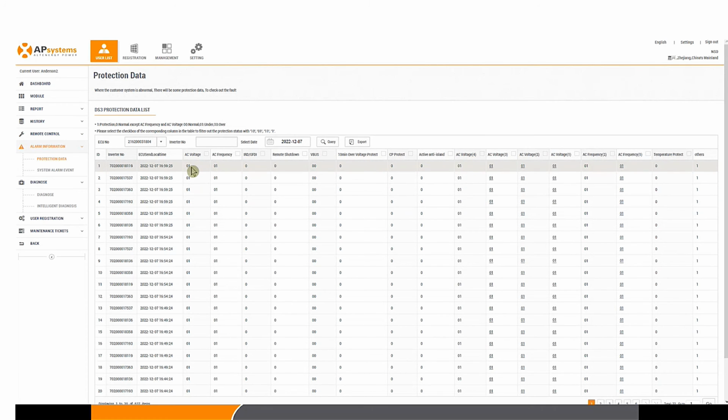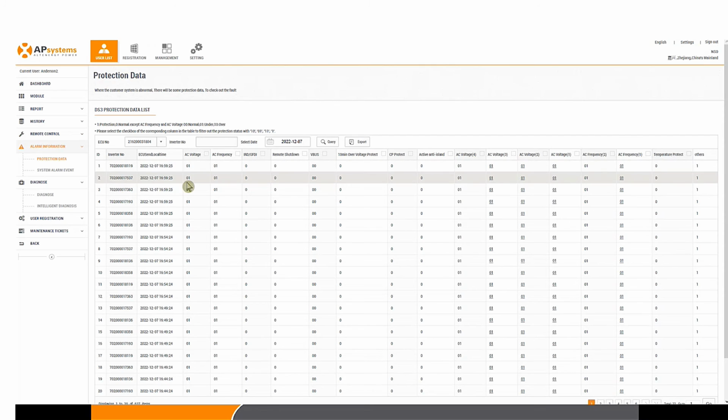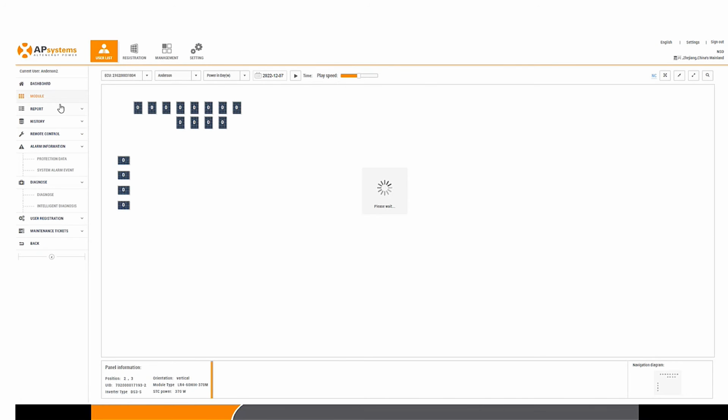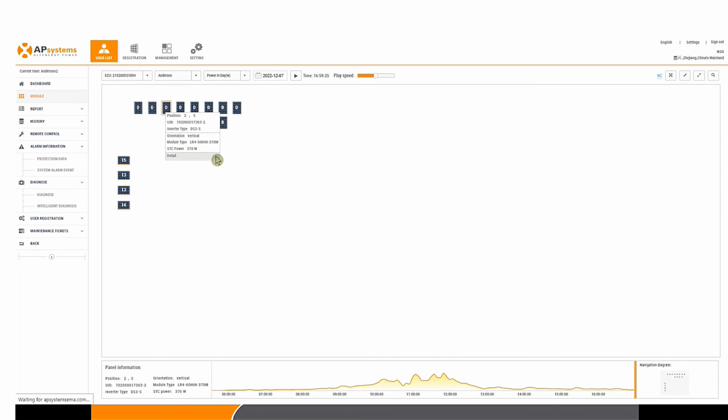But simply, you can just hover over one of them and it says the grid voltage is lower than the inverter AC output voltage limits. So you go, okay, what does that mean? I can tell straight away what it is, but it's something wrong with the AC voltage. Okay, so what you want to do is you then go back to those panels, you click on detail,